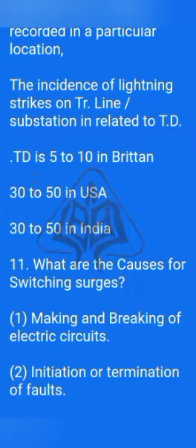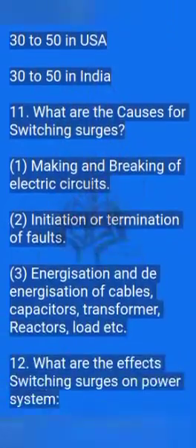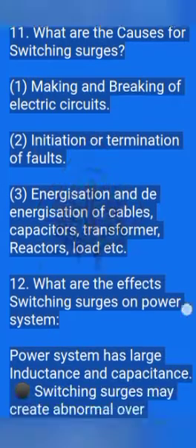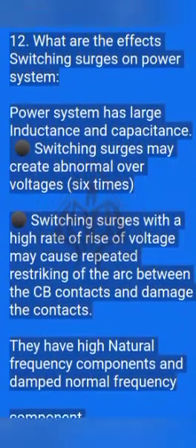11. What are the causes for switching surges? 1. Making and breaking of electric circuits. 2. Initiation or termination of faults. 3. Energization and de-energization of cables, capacitors, transformers, reactors, loads, etc.